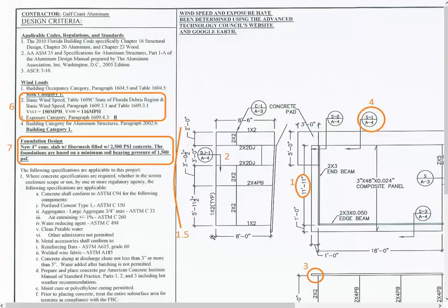And what you'll notice if you go over here to 1.5 is that if you add up the sum of each one of these little numbers, 5 feet 11 and a half inches, 3 feet and a half inch, 3 feet exactly, and 2 feet, right here, you will be at precisely 14 feet. So when you're looking to see what size the actual structure is, it's important that you add up the walls as opposed to the roof, because the roof is getting some subtraction for an overhang.